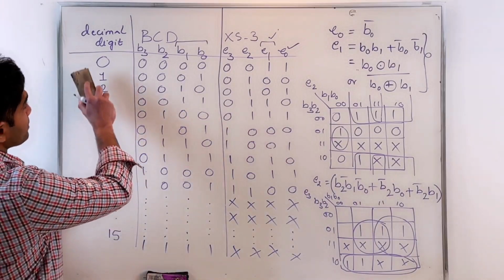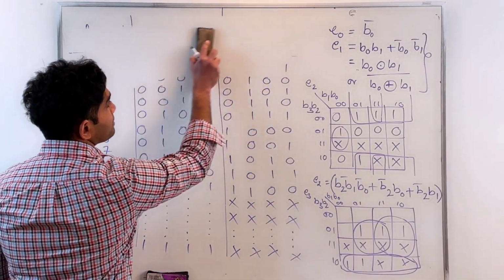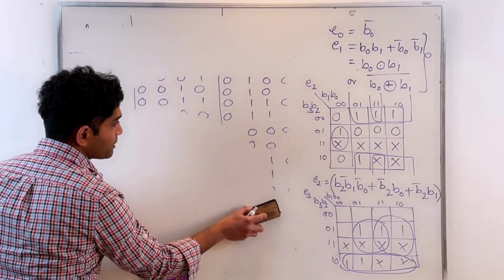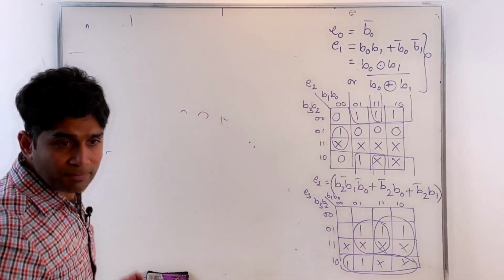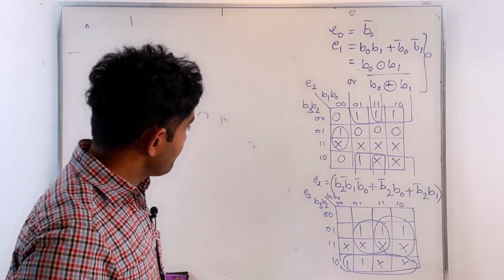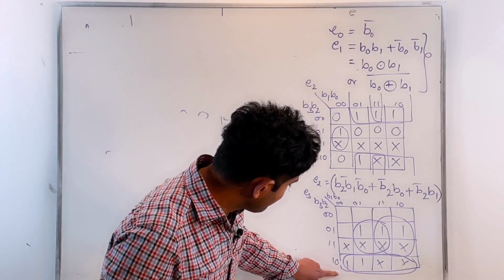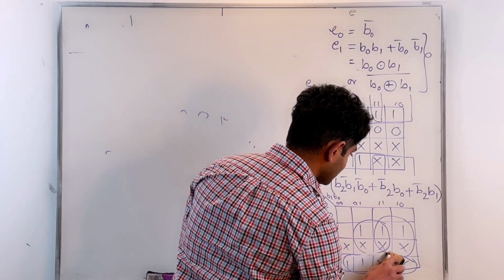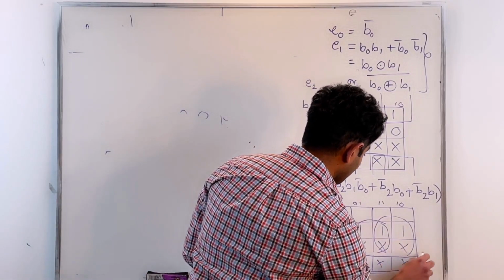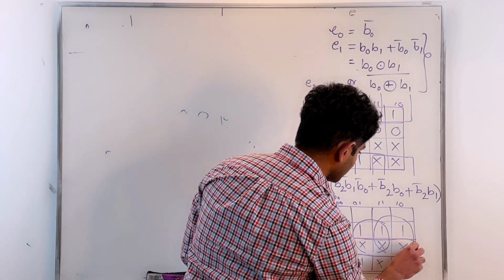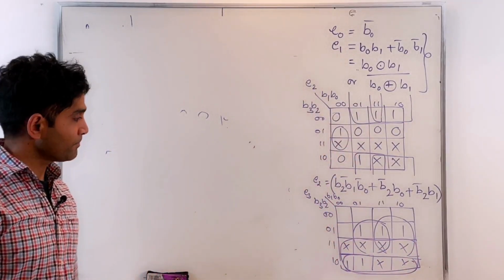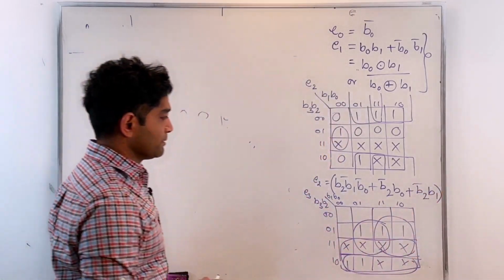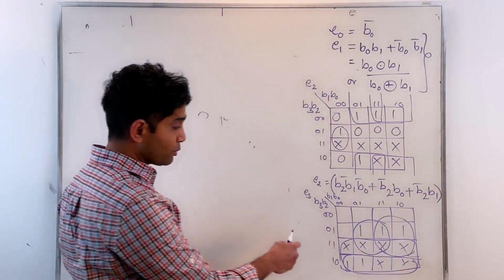Now I don't need this truth table anymore. I'm going to obtain all the information from the truth table. Now Professor? Yes. So for the bottom row there, could you include the next row up of all the don't cares? Oh, you're right. You're absolutely right. I can actually use these in a larger combination. That's right. Thanks for pointing out that mistake. Yes, that will be the prime implicant in this case because I can use those to my advantage.